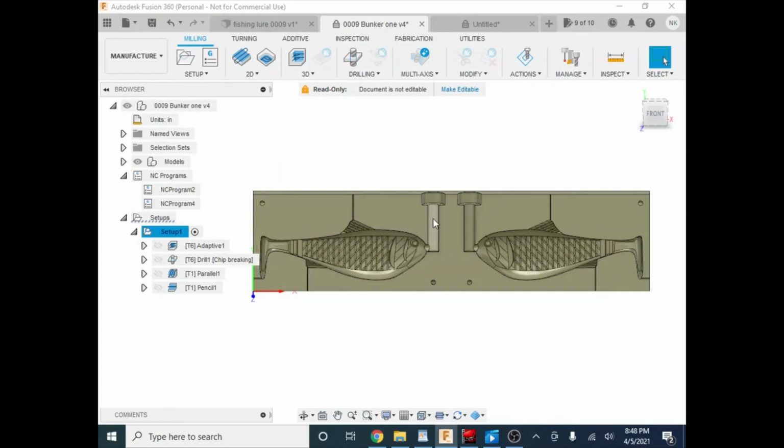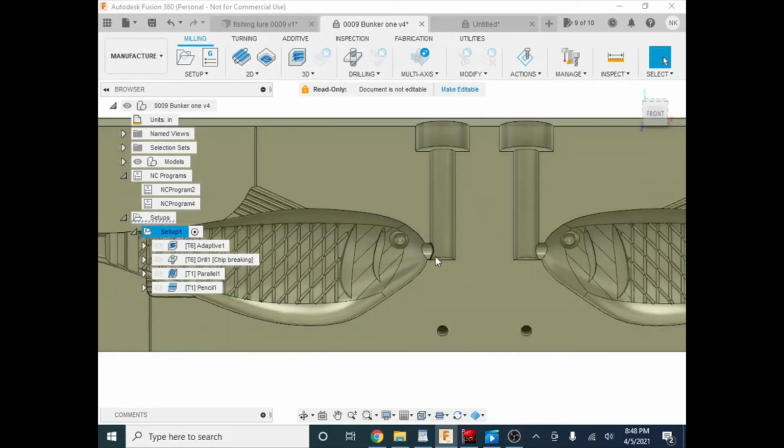One thing that I did have to do is widen this out, because the bait is so large, I did have to create some type of reservoir in here. So when the outside cooled and the inside was still molten, it could pull in extra material. So I did have to widen up the mouth. This was too small, and I had to make it quite larger, as well as increase the shaft diameter to hold more liquid plastic, so when this cooled it actually sucked it in.